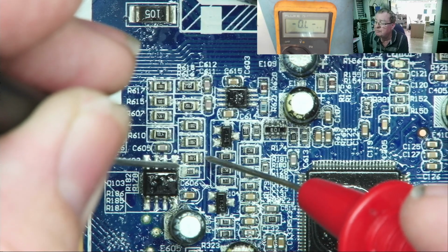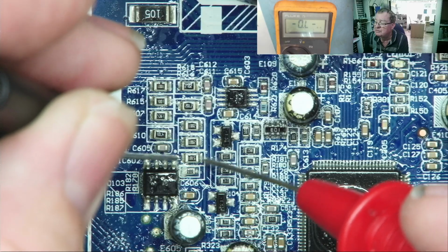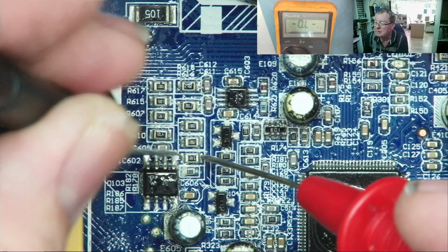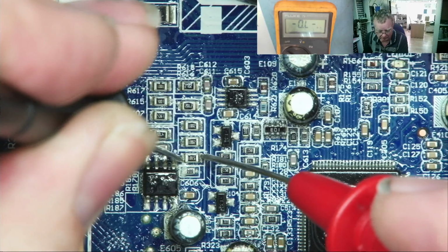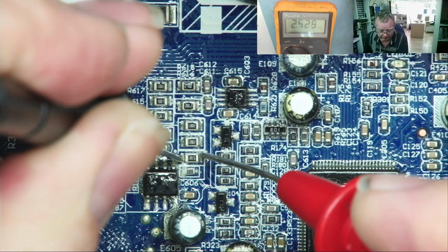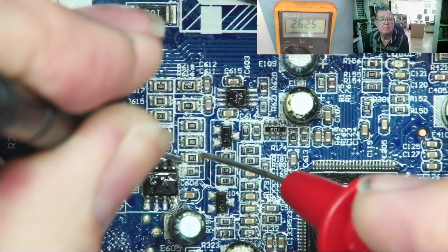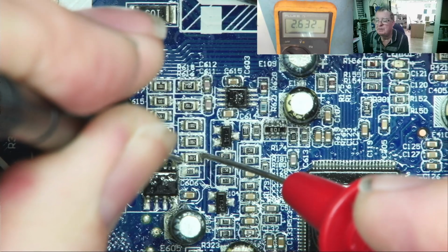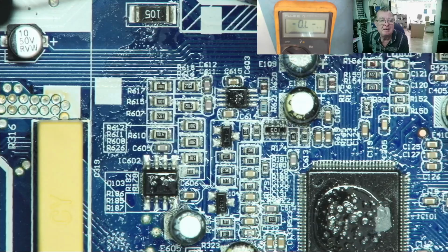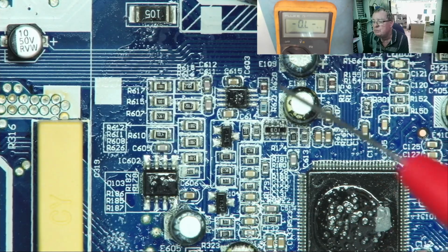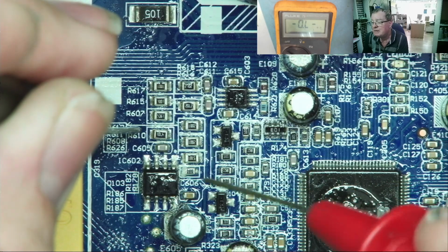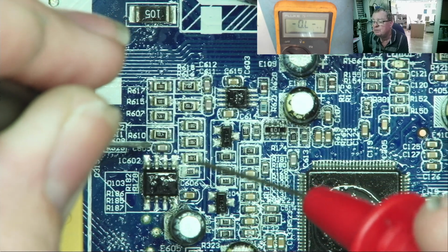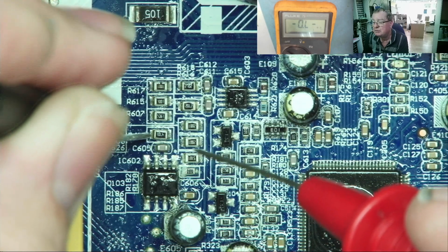Let's look at this one, 5100. Yeah, 1 more 0, 5.1K. You see that reads lower. Yeah, 2.6. Can you see that? 2.63. That is not a faulty resistor. Resistors do not fail by going low in value. It will read low simply because there's something else in the circuit affecting the reading.